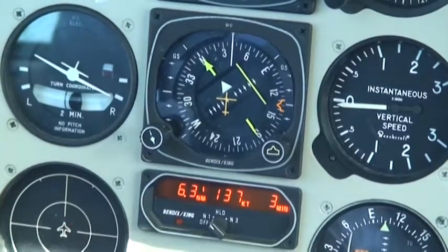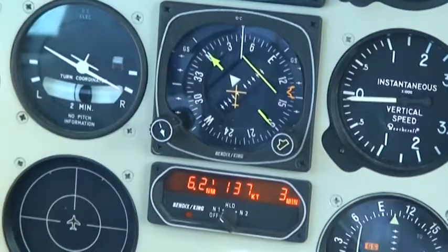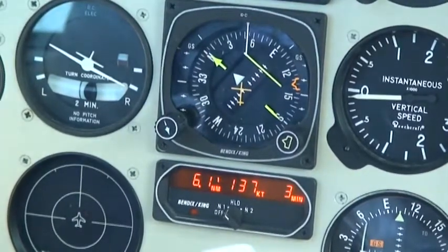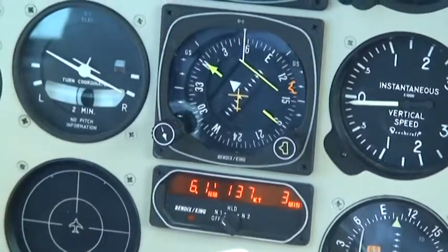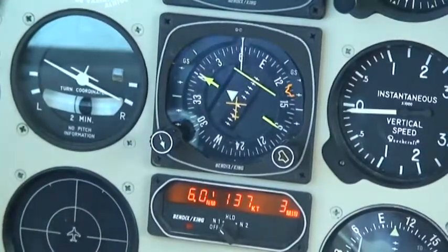While the miniature airplane responds with the airplane's banking action, it mimics roll. However, it actually directly indicates rate of turn. This means that in a 30-degree bank turn, the airplane will show a bank on the turn coordinator, but it may not actually be a 30-degree bank.